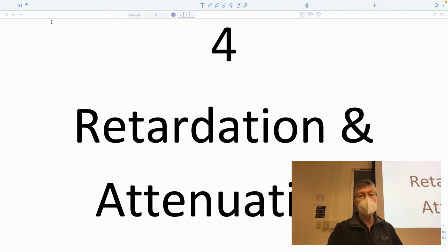And so I suppose that you'd expect that if you're potentially removing components from the flow system and anchoring it to the static porous medium, then if you assay water downstream in those non-conservative systems, the concentrations in water would be both lower, because you've lost some to the solid medium, and also be progressing more slowly down gradient, because you've been taking it out of the porous medium and not allowing it to go downstream. So the two words, retardation and attenuation, refer to each of those things.